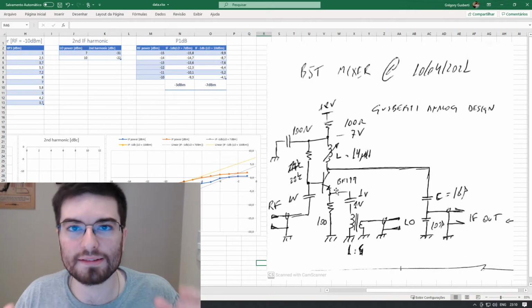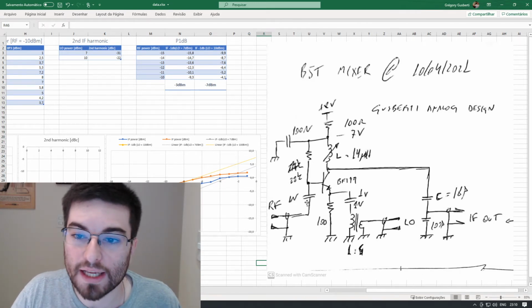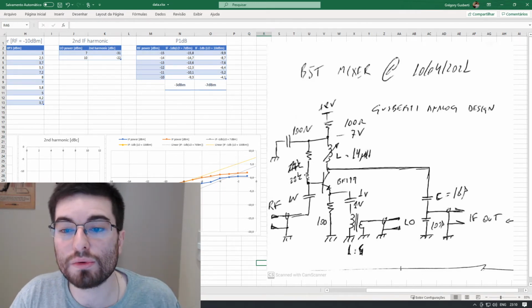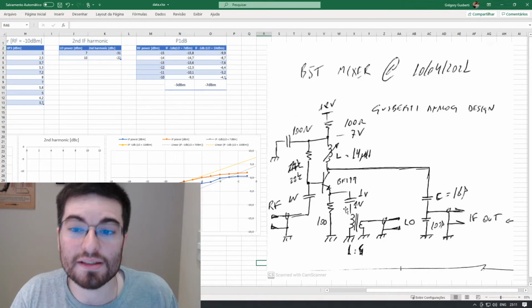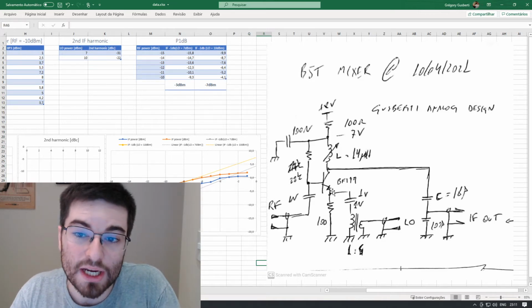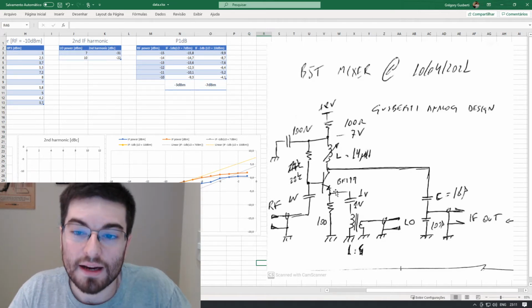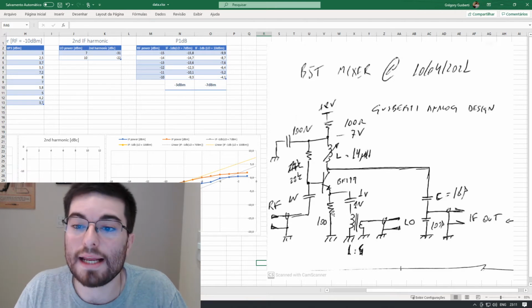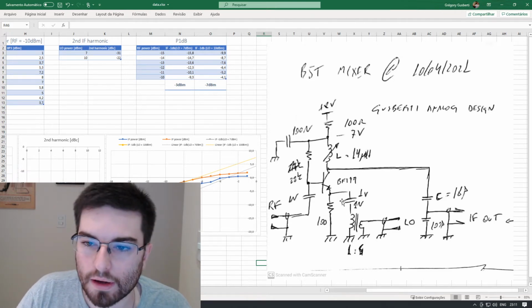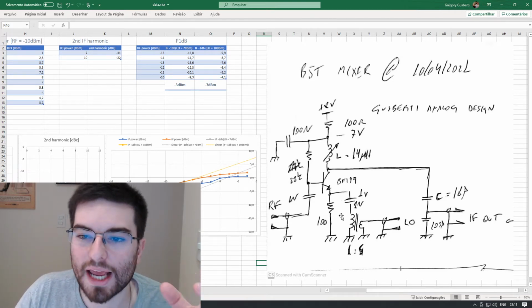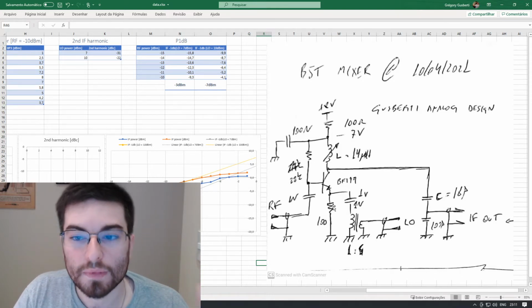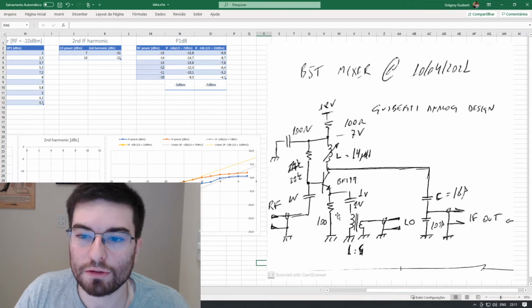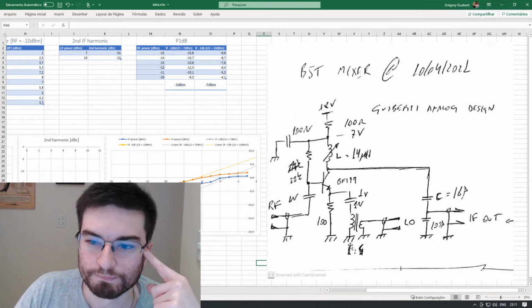The square term of the expansion of the exponential relationship between the collector current and the base emitter voltage is what gives this stage the mixer characteristics. And this is why this stage works, because we have a term in the relation between the current and the base emitter voltage that is squared, and this is the multiplication factor that will multiply the two signals.